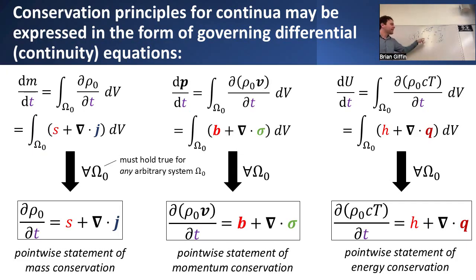But the idea is this: it doesn't really matter what you choose for this particular reference domain. In fact, this condition, mass conservation, momentum conservation, energy conservation, all these principles should hold in a universal sense, which means that if I choose any possible kind of reference volume or collection of material points to begin with, then throughout the whole universe, any possible reference configuration of material points should satisfy these different conditions.